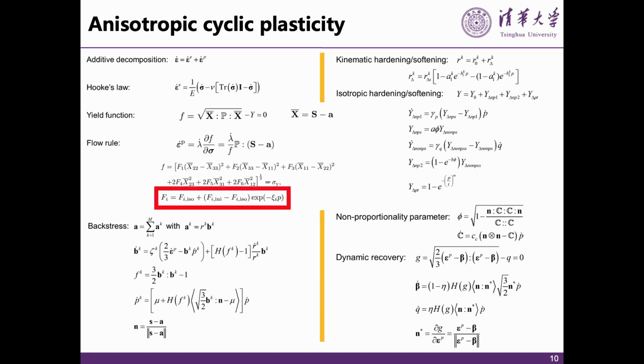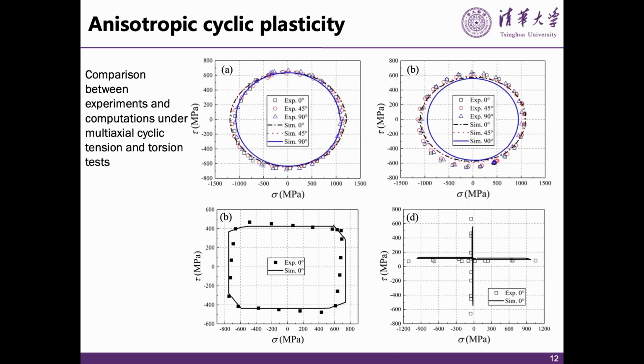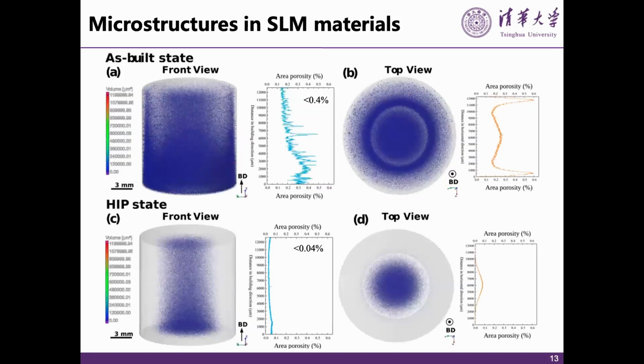Anyway, the results look very interesting. We see the comparison between experiments and computation. We performed cyclic, monotonic, and multiple tests, including non-proportional cyclic strain curves and so on. Even with cross form, the agreement is reasonable. For industrial application it would be good enough. That means the material's property is slightly anisotropic, but we can use the conventional model with modification to cover this.